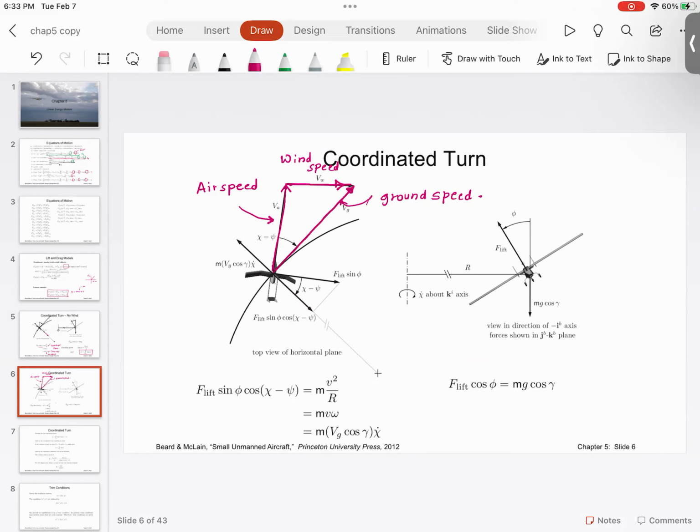Now, one important thing is aircraft do not have speedometers, because the wheel speed does not give you a relationship of how fast the aircraft is going. What aircraft have is something called the pitot static tube. If you look at any aircraft, typically at the nose on the left-hand side, you will see a small pipe extending out.